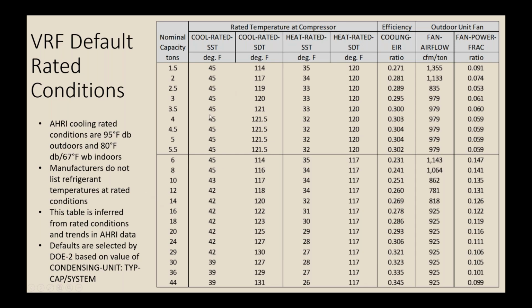Basically, there's a process to get at these numbers by looking at the outdoor temperature and the indoor temperature, and accounting for the dynamics of the coils and estimating what the refrigerant temperatures would be at design operating conditions for the different sizes of equipment.